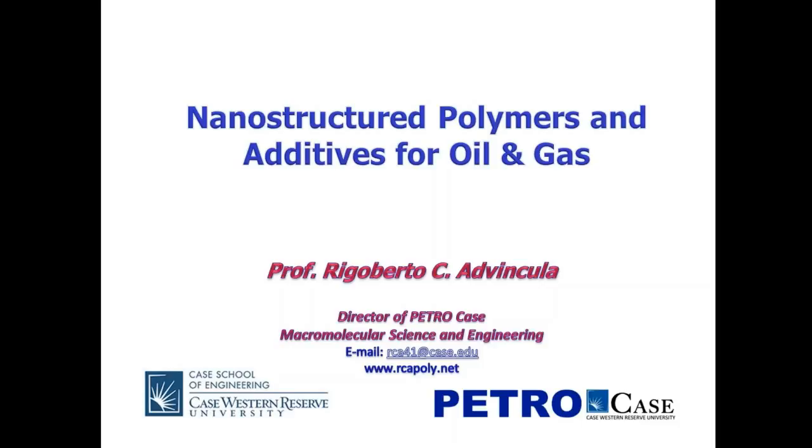Do you think there is a polymeric lining for geothermal pipes and equipment that can survive at high temperature and brine conditions and simultaneously prevent silica scaling? We're working on that. That is, in fact, the challenge that we'd like to face. We're working on a high temperature thermoset with good lubricity when coated as a film and cured thermally.